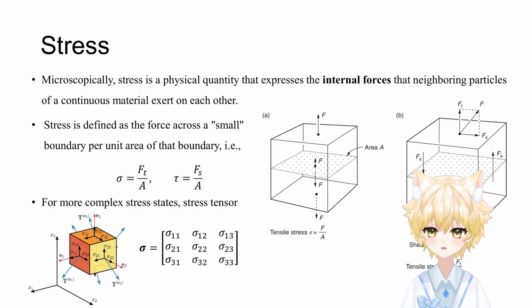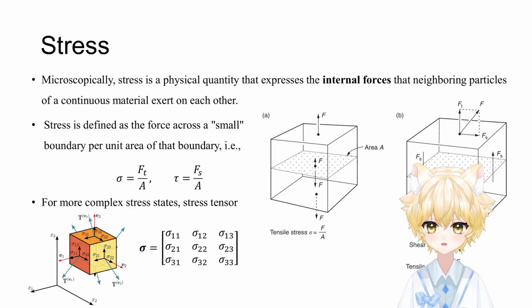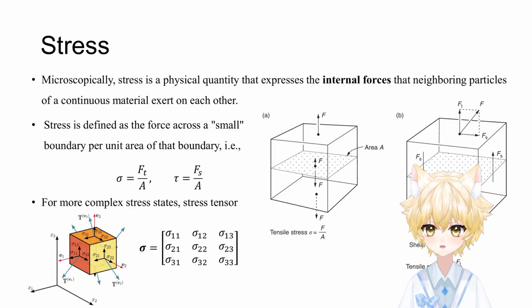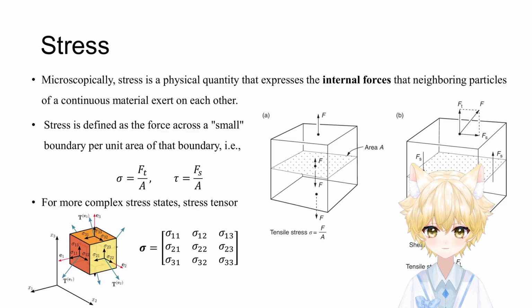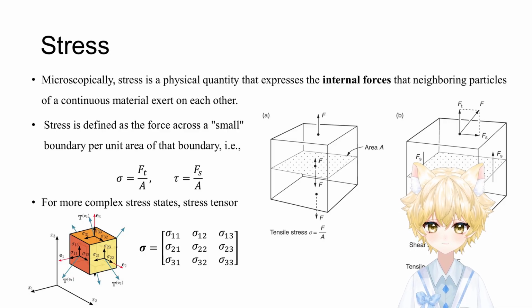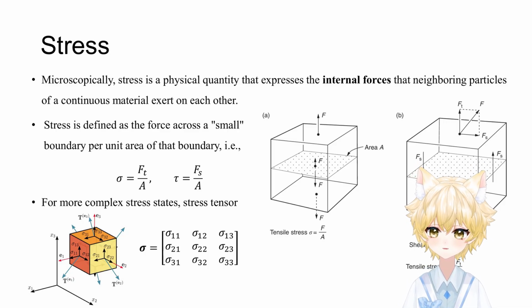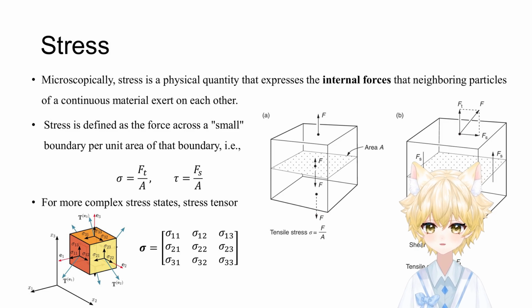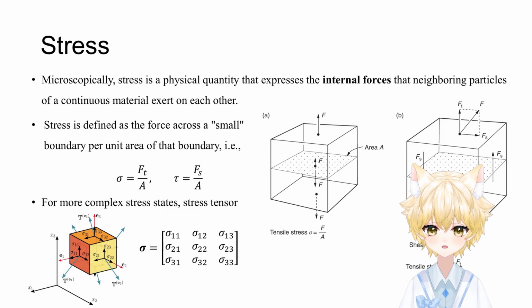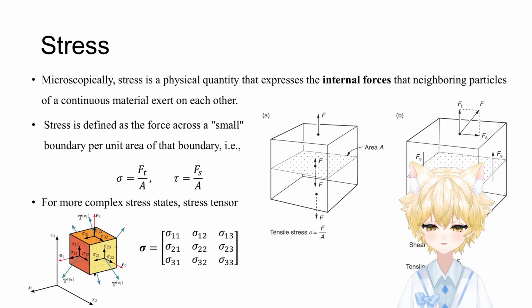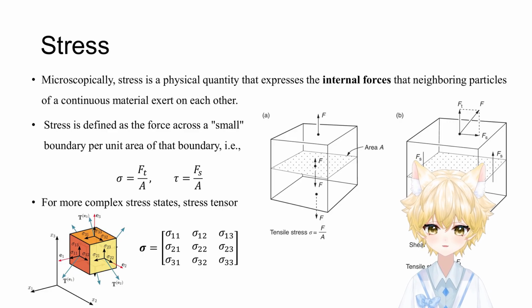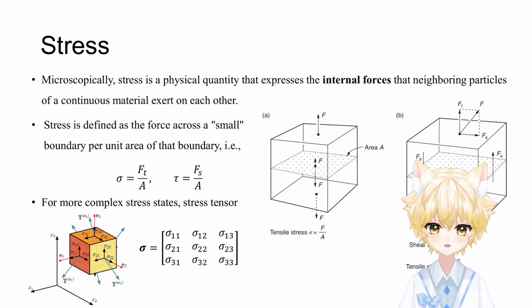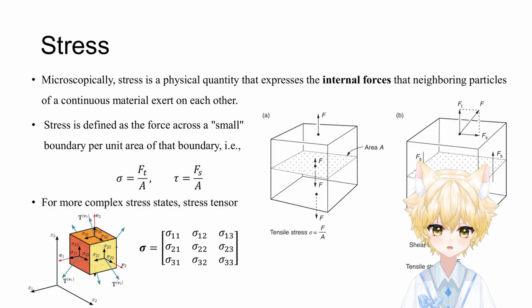This particular stress is caused by a force pulling at right angles to the face. We call it the tensile stress. Suppose now that the force acts not normal to the face but at an angle to it. We can resolve the force into 2 components, one Ft normal to the face and the other Fs parallel to it.